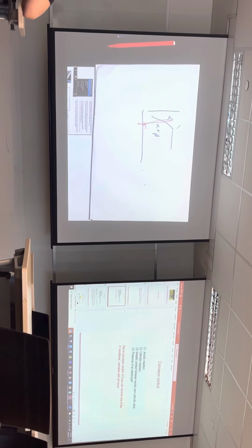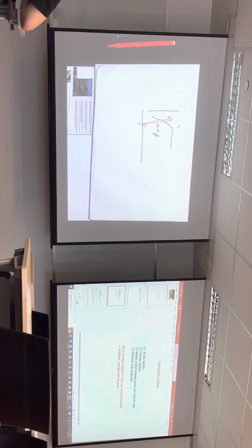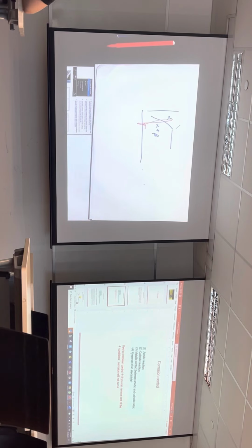But I don't know where it intersects. It says corrosion control, is it? The sealant. Actually, if you look at this, whatever is coded under the manufacturers, when they apply sealant, under which part of corrosion control is it? They are actually trying to remove the presence of electrolyte. So if you understand the principle, you understand that corrosion needs to have four things. They are just trying to kill one of those.